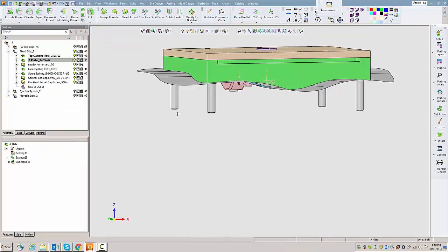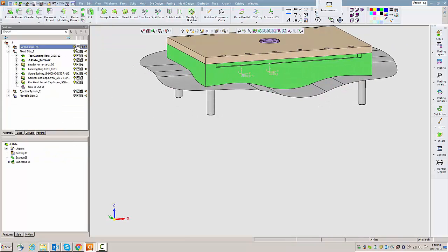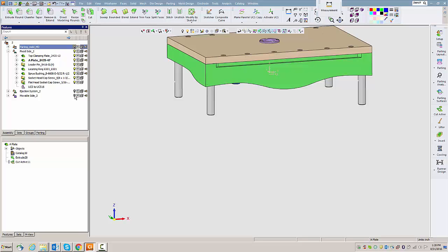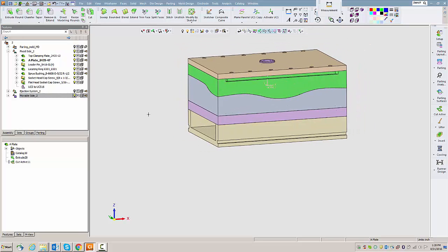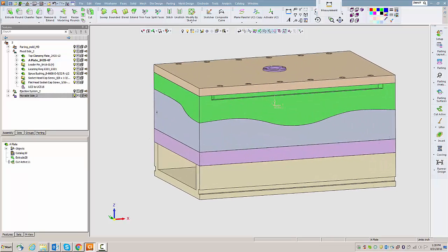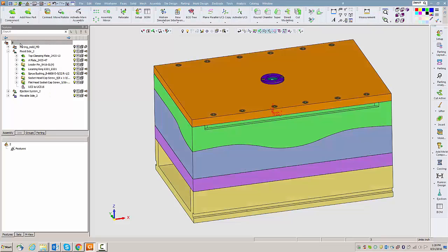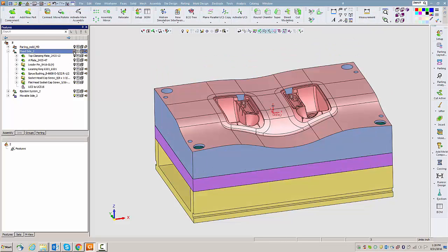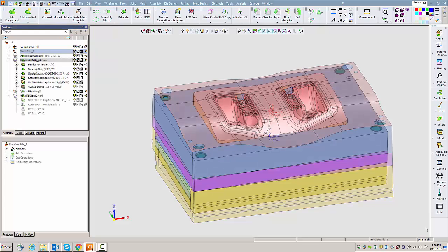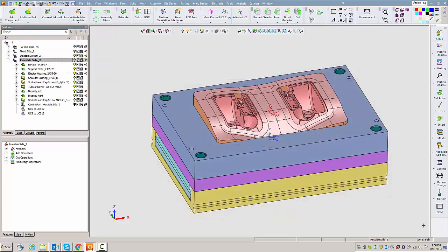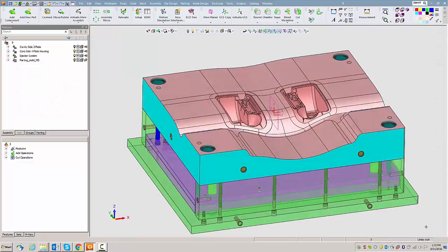Again, it's possible to use other methods to do this. One would be to order the A and B plate oversize when selecting the mold from the catalog. And everything that you've seen can apply to different styles of molds, such as this one for direct cutting to the A and B plate, multi-cavity insert molds, and non-standard custom molds.